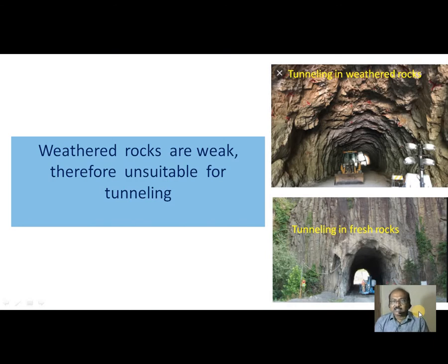Weathered rocks are weak and they are unsuitable for tunneling. We can compare these two pictures. In the above picture, the tunnel is passing through a weathered rock where so much rock is excavated rather than the exact perimeter of the tunnel.